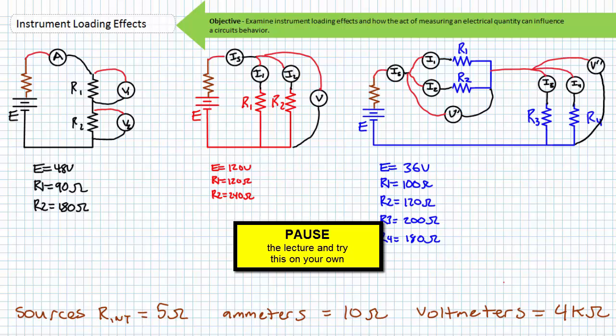I'm asking what the ammeter and voltmeters read at their given locations. Be aware that the single ammeter in this circuit would be measuring source current, but it isn't really measuring I1 or I2 because a portion of source current is diverted through the voltmeters in parallel. We'll discuss these subtleties in the analysis.